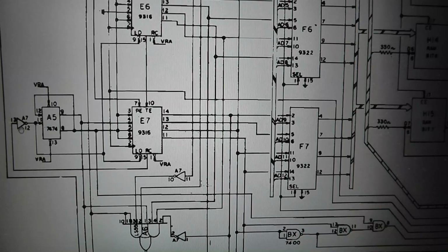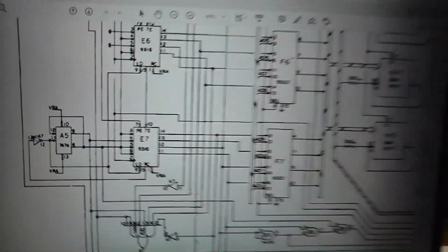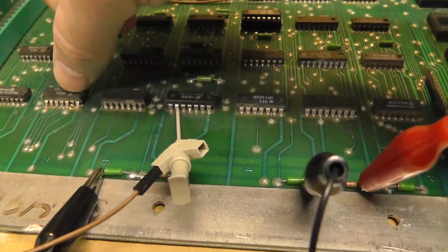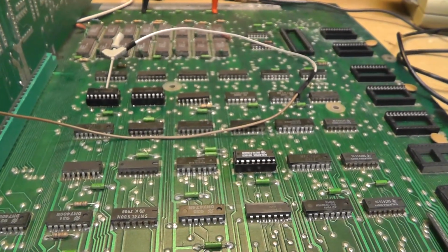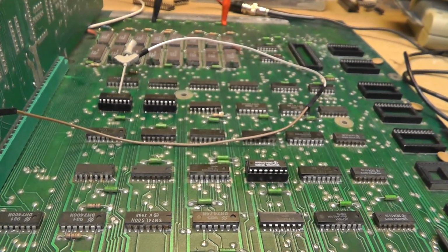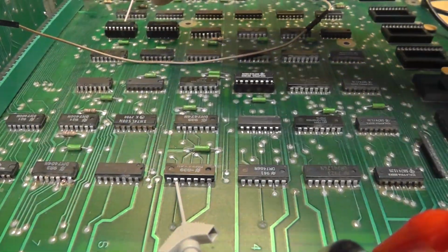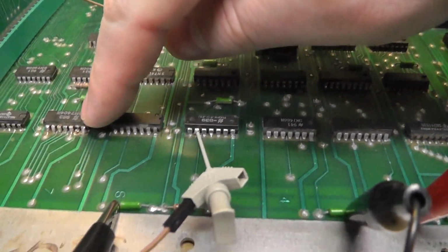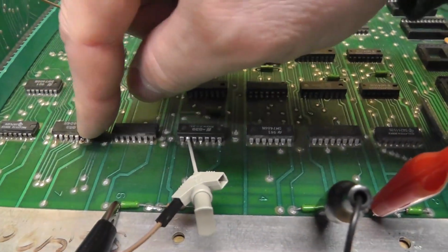So I went to look at this A7 chip, and it just looks bad, and I'm probably going to replace it. Let me see. That's the best thing I can do. I tried clipping the one leg, pin 13. Is that right? Yeah. Pin 13, which comes from the ripple carryout over here. It's actually also where I had to put my jumper. And I don't know. I'm just hoping that this chip is bad.